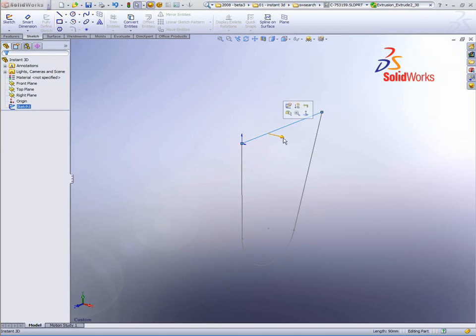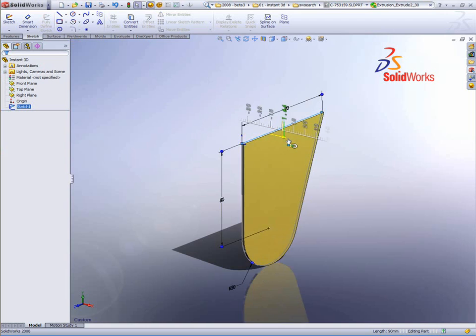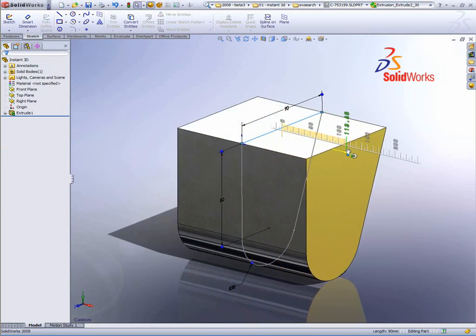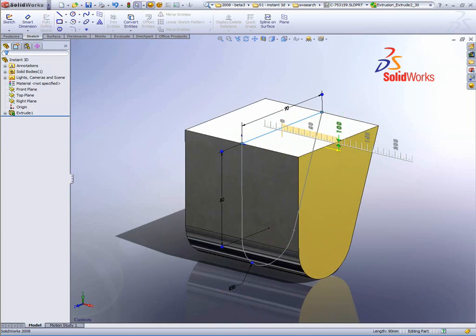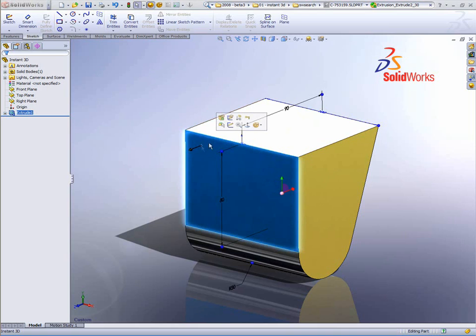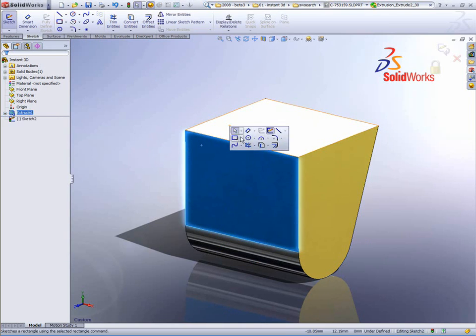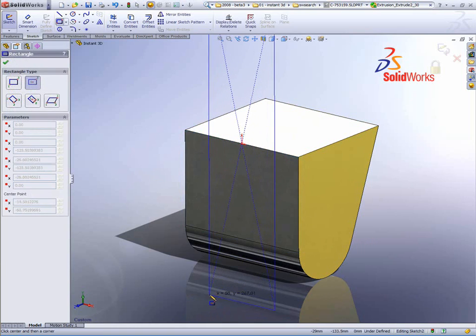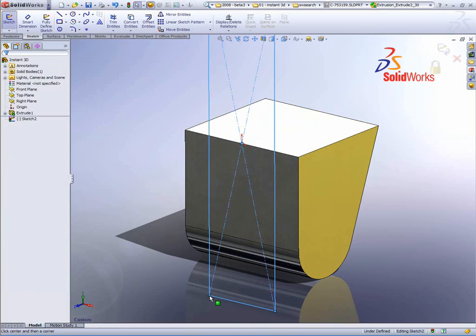By choosing the sketch, you see I get this arrow, and I can drag this arrow in either direction and start adding the geometry. Holding down the M key gives me a mid-plane extrusion, so I can extrude about the mid-plane. Just by selecting a face, I have commonly used commands. In this case we're going to access a sketch, and then access a corner rectangle, one of the new rectangle tools for SolidWorks 2008. And we'll quickly add a dimension.